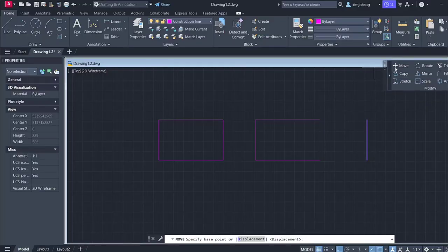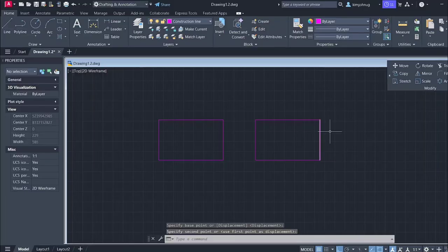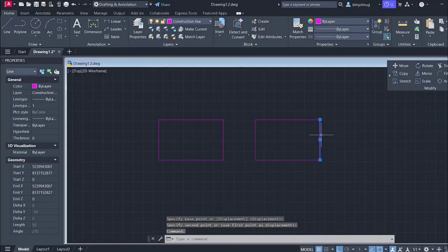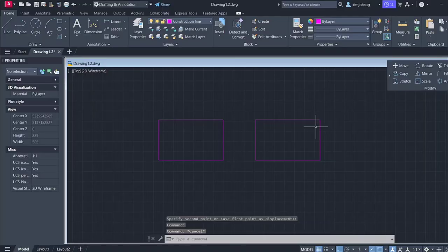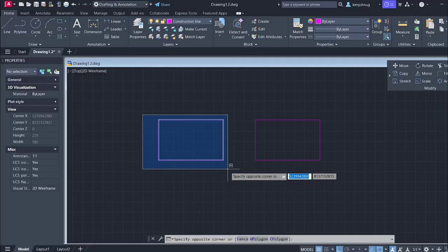So now I've started the tools. We have used the explode. Now we're on the move. Boom. Move it back. So when you're moving an object, always move it corresponding to the endpoint you want to join it to. I'll explain that further. So if I want to join the one for the rectangle drawing using the line tool, which are not joined together, I do the same thing.